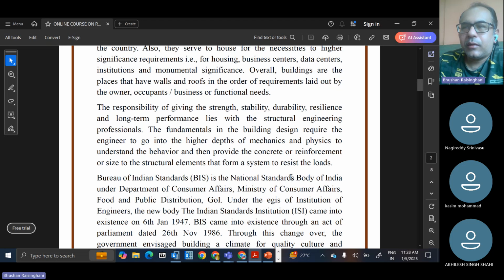A beam connected to a shear wall is released, then a secondary beam of higher depth connected to a main beam of the same depth is released. Both have the same depth, secondary beam and main beam, and there is a release between the beams, just because the reinforcement is not detailed in that particular way. That reduces the stiffness of the full building.